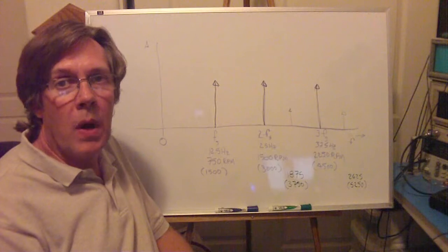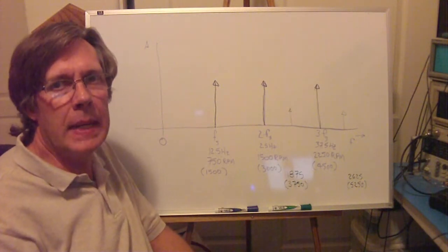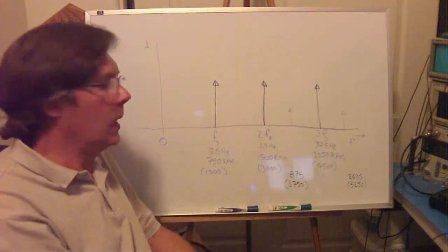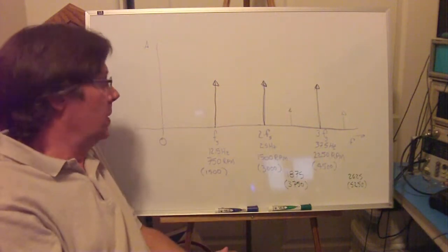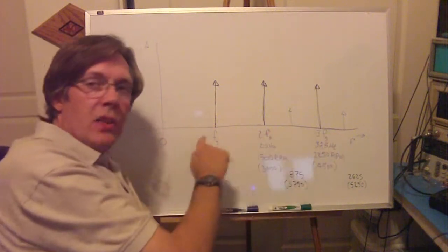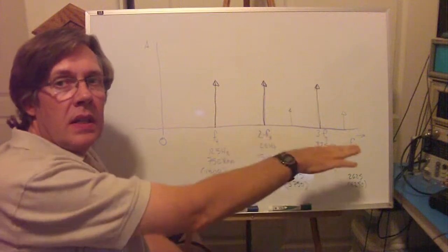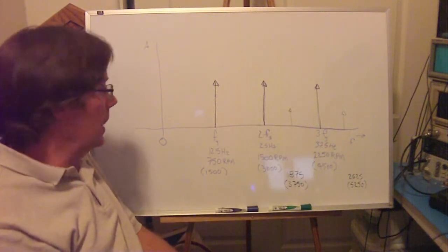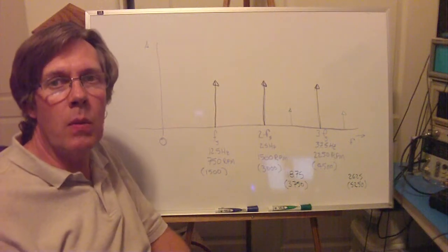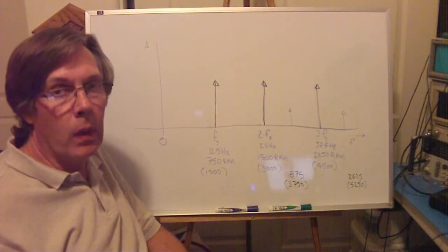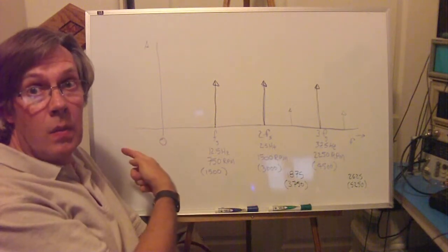So now we're going to talk about what happens in aliasing when we look at it in the frequency domain. And by frequency domain, I mean like our plot is showing here. On the vertical axis, we have energy or power, amplitude. And on the horizontal axis, we have frequency, starting at 0 down here and increasing as we move that way. Now we show 0, but actually when we have something like what we're demonstrating with a rotating system, or if we're sampling with complex values, we can also have negative frequency going the other way.